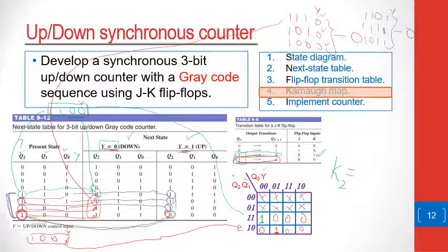Now, having that in mind, we can now formulate the groups of the K-maps. And the first group that we can make, the largest group here, is that. Make that group of 2. And when we make this group of 2, we see that in both cells, the Q0 remains 0, the Y remains 0.